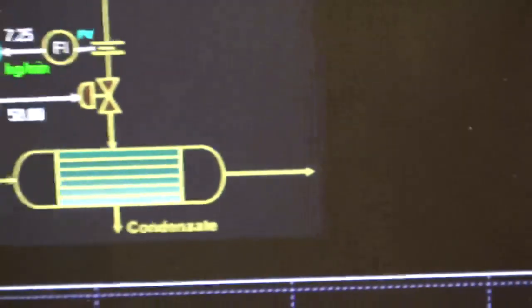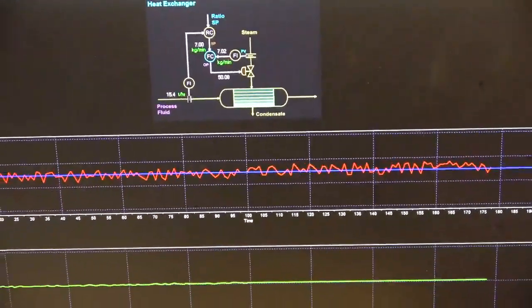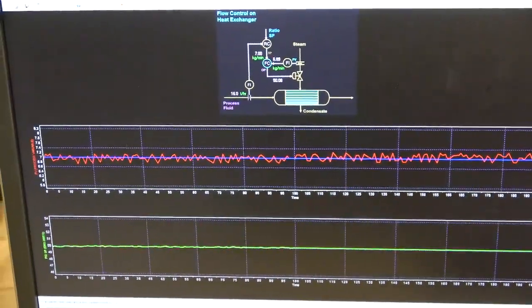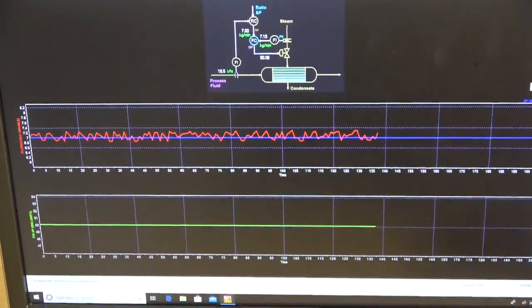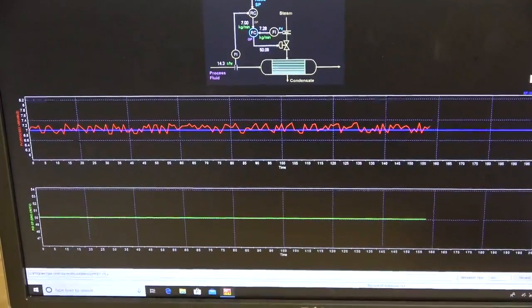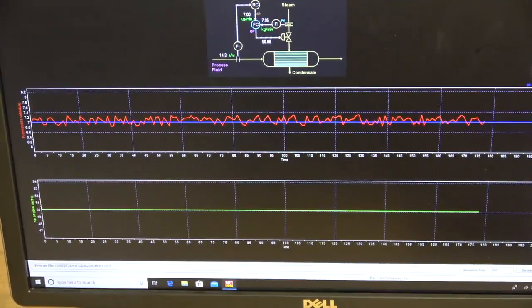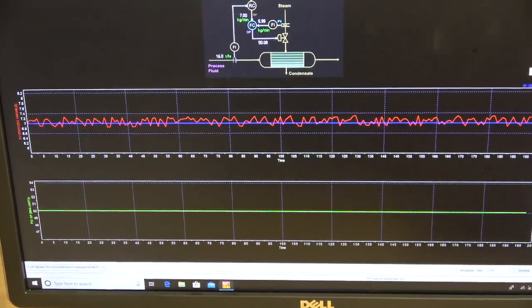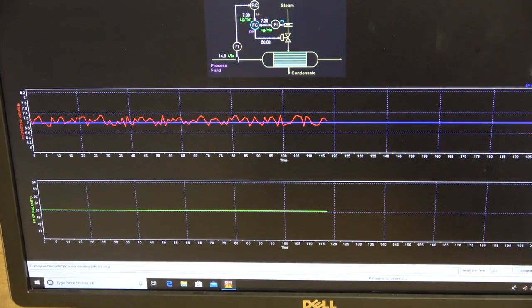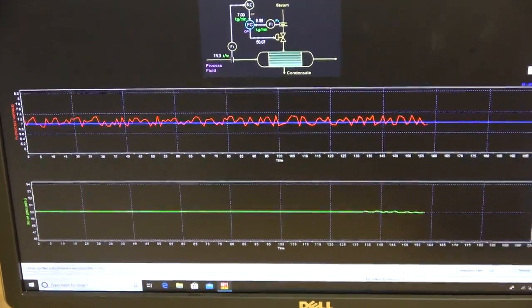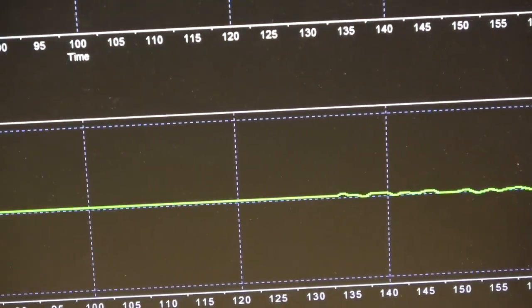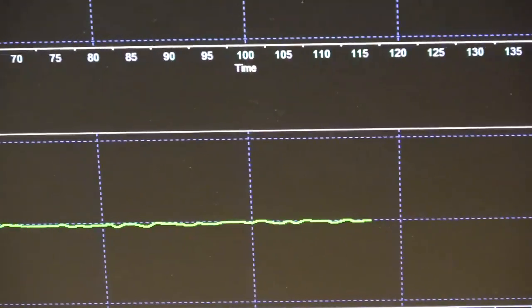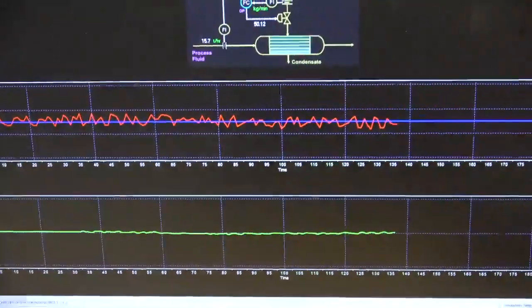And look and see what it did to our screen here. Really doesn't look like it changed much anyway, did it? And it probably won't, because we haven't interjected anything in there. But if you will notice maybe that the output level has stabilized. It's not wiggling a little bit like it was before, when we were in auto. I'll put it back in auto, and you can see. Now it's back in auto, and if you notice, very quickly the output started modulating just a little bit in there. That's the difference in what happens when you go from auto to manual.